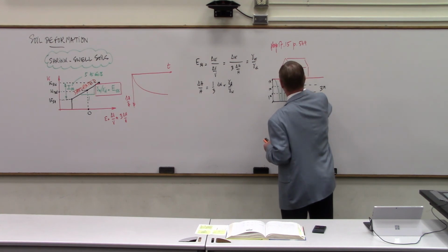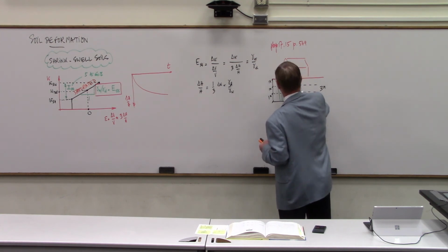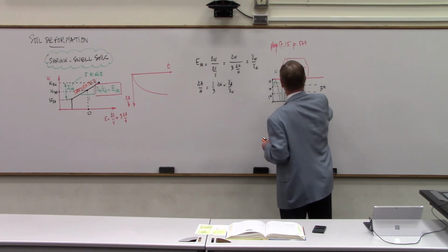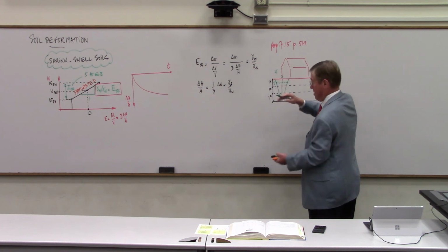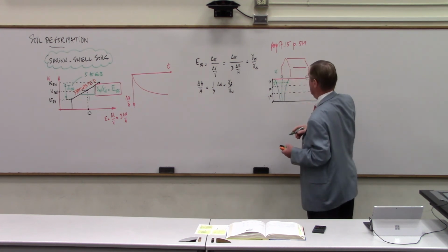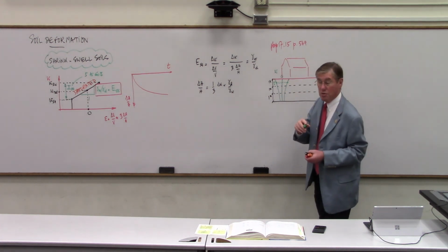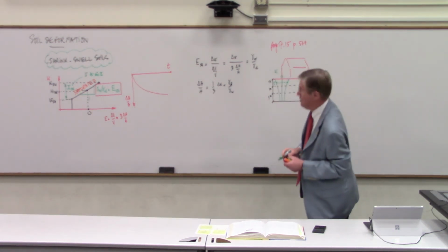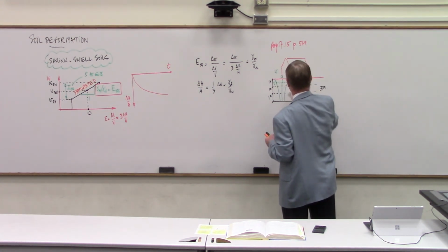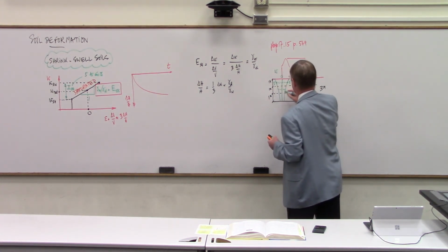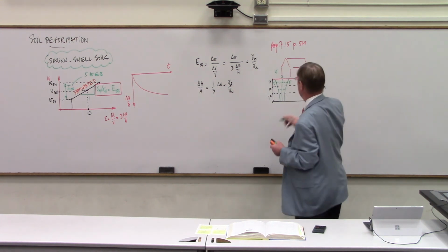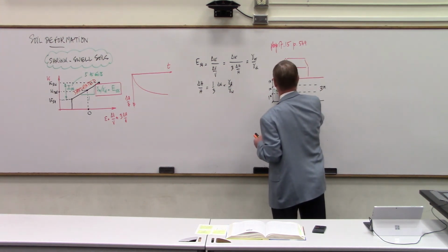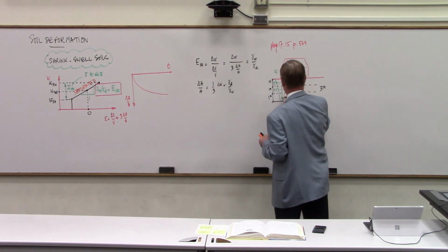So this is 0, and this is W, and here we have 5%. So at that depth, 0.5 meter below the ground surface under the house, the water content during the summer is going to be minus 5%, and during the winter, plus 5%. Okay, on the other side. At that depth, it's going to be 2.5%. And here it's going to be 1%.